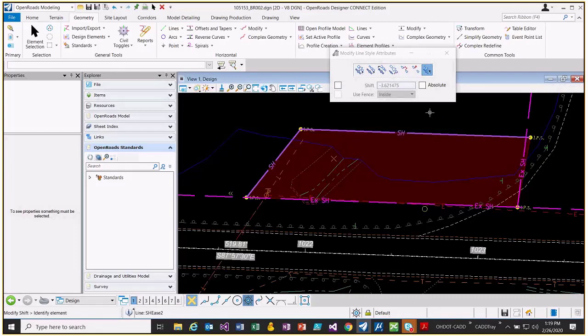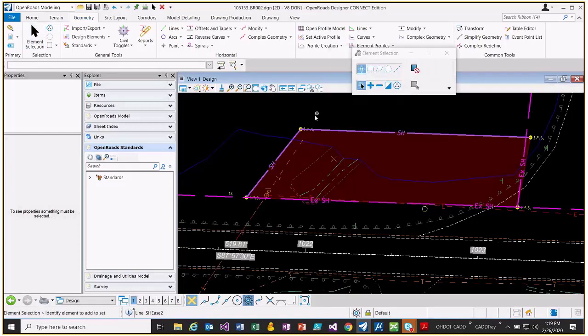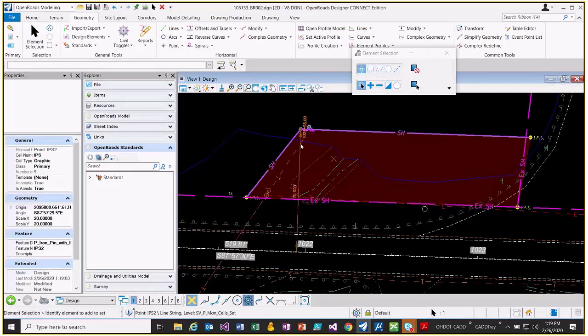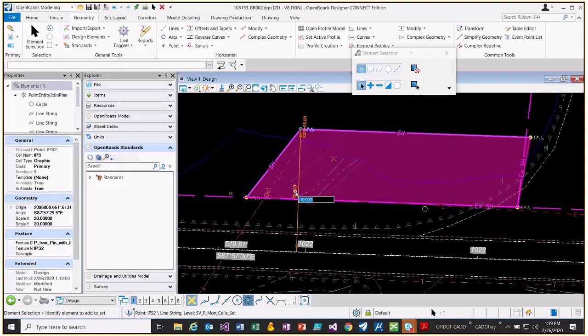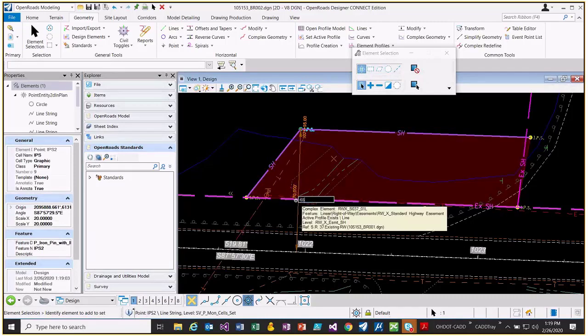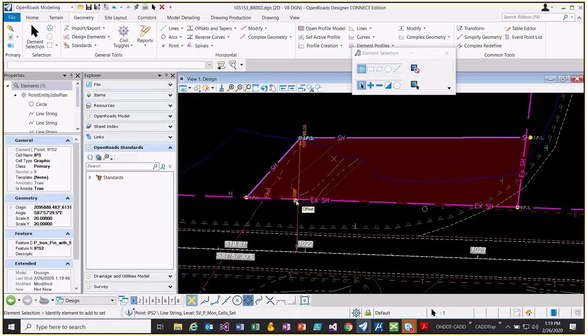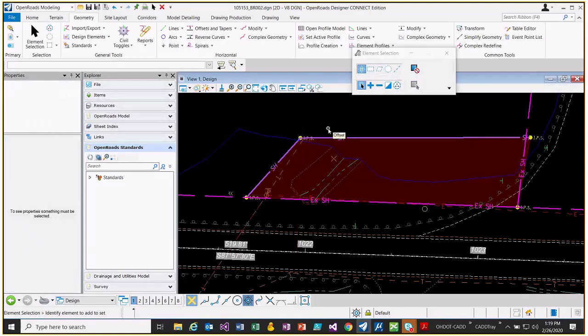little bit. The only thing to keep in mind on that is if I would make an edit, so let's go back and change this to -65, it has to redraw that line. So it's going to restart that line style cycle from its original location when it redrew the line. So just keep that in mind if you make those edits, that you would lose that shift and you would have to reapply that.